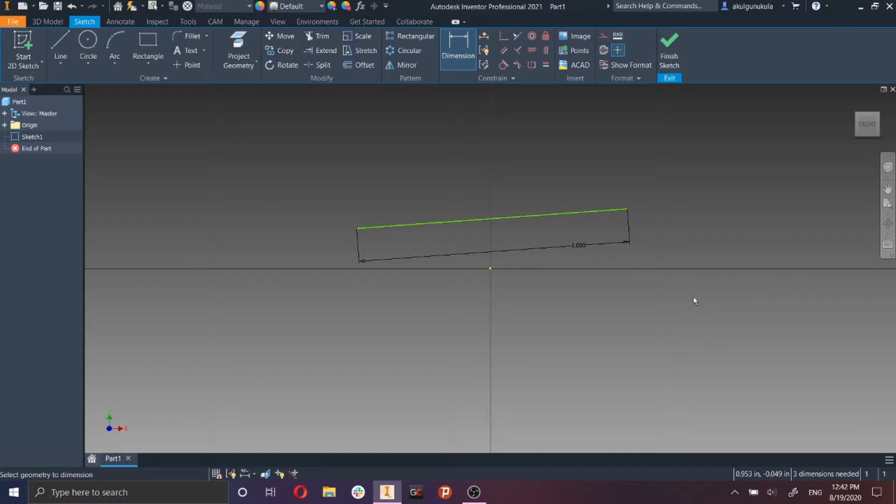I'll show you what that is in a moment when I edit this. So let me show you how you can edit it. So instead of deleting this and then redimensioning it, you can do it one of two ways. One, if you already have the dimension tool selected, you can left click on the dimension and then you can just type in what you want. Let's say 1 centimeters to show you. So now you'll see that when I press enter or the green check mark, it'll change to 1 centimeter, but it'll be 0.394 inches, which is 1 centimeter just in inches.